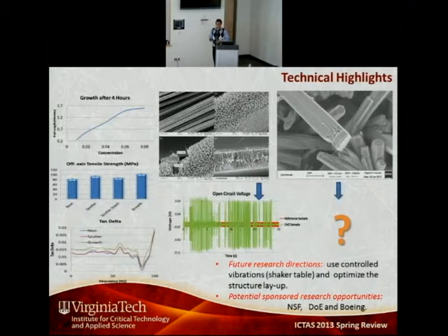So first we start with the growth of zinc oxide. So the growth procedure here is a hydrothermal synthesis technique. So we are putting the woven carbon fiber in a chemical solution composed of HMT and zinc acetate. So we start with varying the parameters in the growth procedures in order to come up with the optimal parameters.